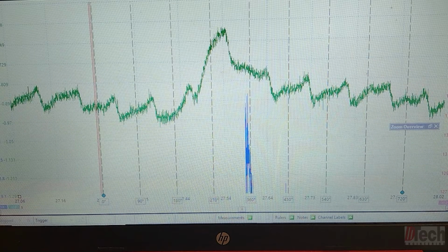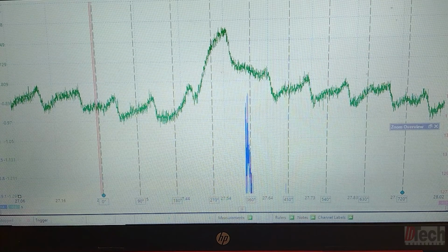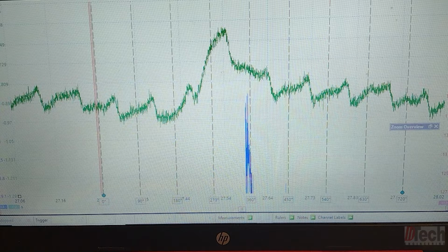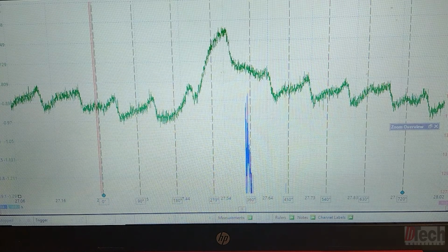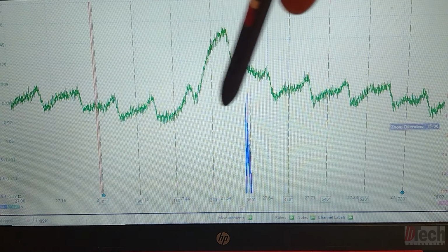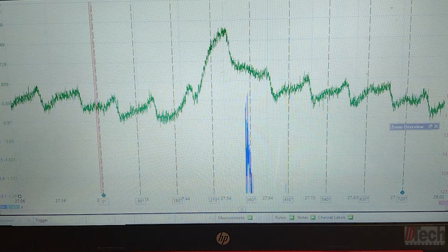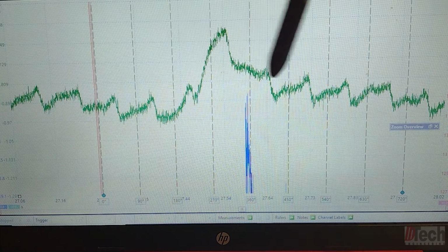Now to break down a little bit more in detail the intake waveform, that's going to help us give an even more fine-tuned assessment or diagnosis. If we look at the trace, we are going to look for intake pulls from each cylinder, and you want to see 8 even looking pulls. Obviously we've got a motion that doesn't keep it all at the same level or all near the same level.